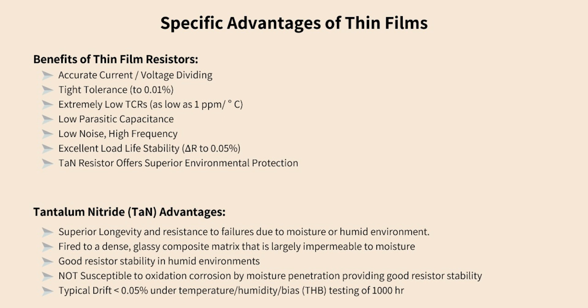These characteristics make tantalum nitride an excellent choice for applications where environmental protection and long-term reliability are critical. Thin film resistors, and particularly tantalum nitride variants, deliver superior precision, low noise, and exceptional environmental durability. This makes them indispensable for applications where accuracy, stability, and reliability cannot be compromised.